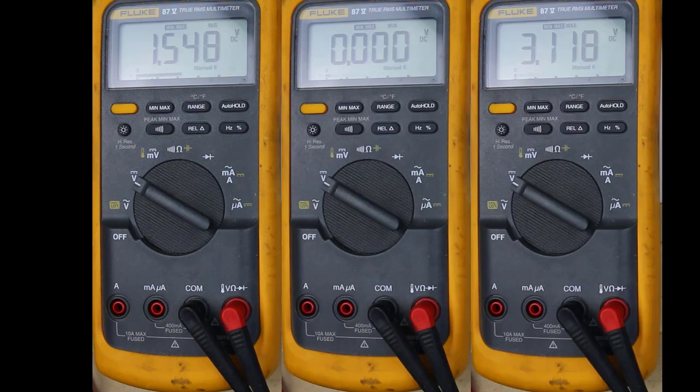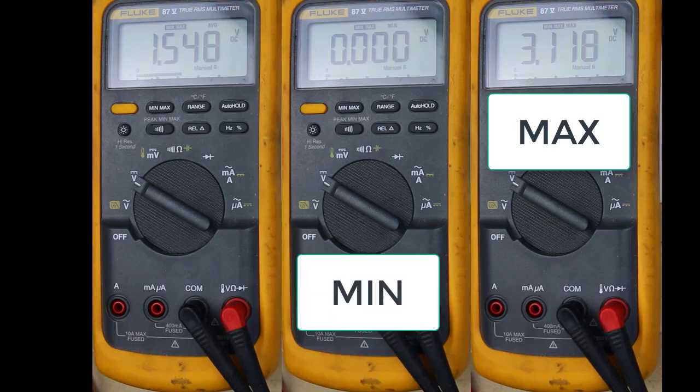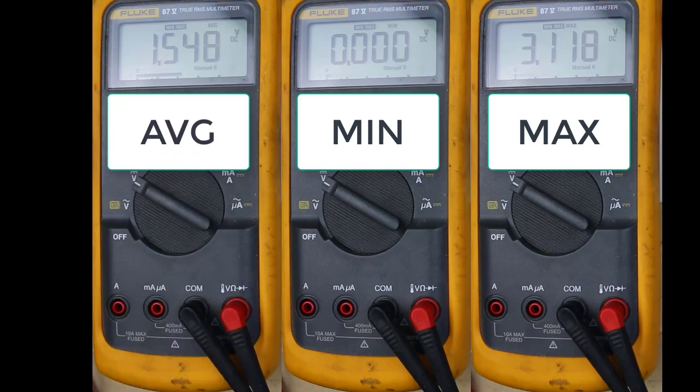Here's a screenshot of the 3 values that I measured on my breakout board. Yours might be slightly different than this. I got a maximum voltage of 3.118 volts DC. The minimum voltage was 0 volts, and the average voltage was 1.548.